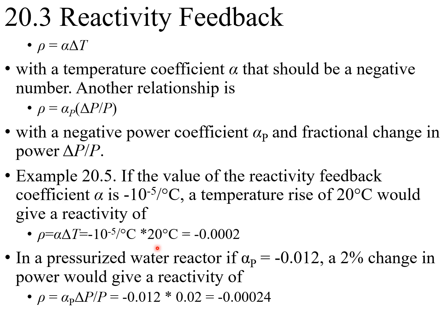So the system power is going to automatically increase a little bit so that the system temperature will go back to its normal set point. Next, we get alpha P. If alpha P is equal to this value, pay attention that this alpha P will have no unit, because alpha P is going to be multiplied by a power ratio which has no unit either.